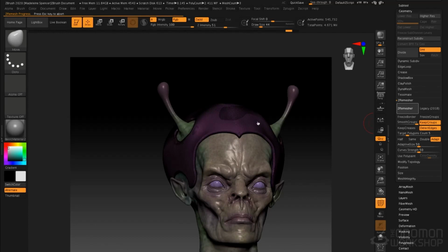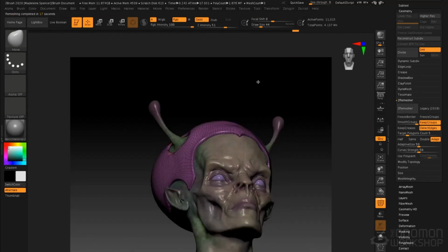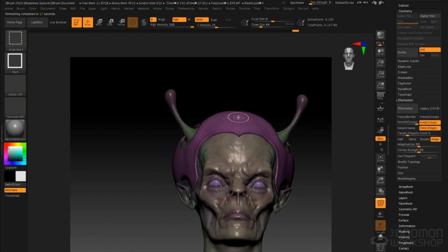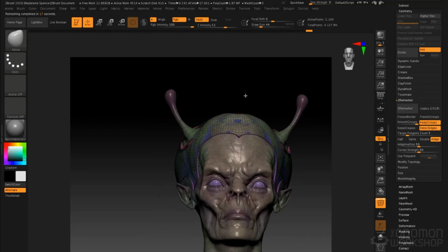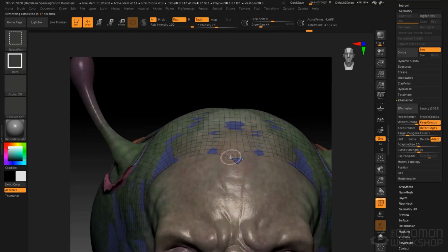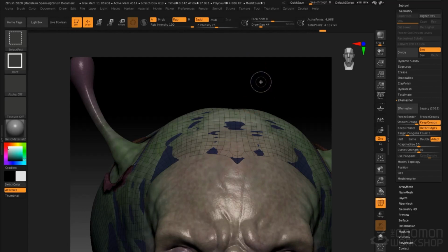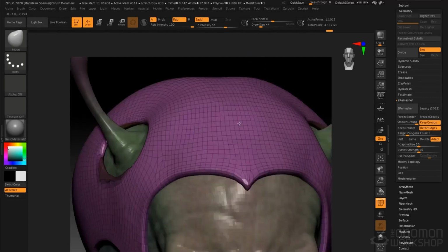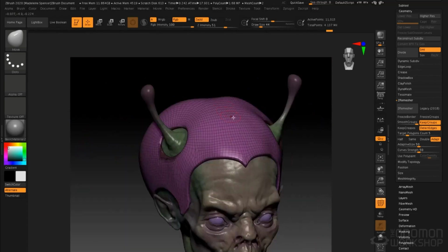So we'll let that work through the remeshing process. And there we go. So if we Control-Shift-Click on each group, you see that they are maintained. So let's hide the outer shell, hide the thickness, mask the inner shell, and then reveal everything again by Control-Shift-Clicking on the background.